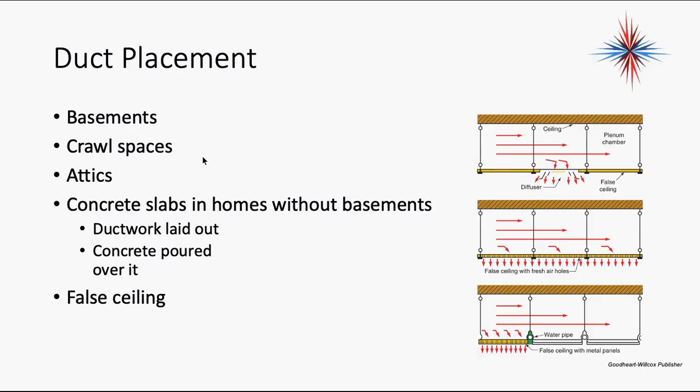Duct placement makes a big difference. I can place ductwork in basements, crawl spaces, attics. I could put them right into concrete slabs without basements. We put in the ductwork first, we lay it out, we pour concrete over it. Bad idea. 1970s construction, not done anymore. We can hide it in a false ceiling.